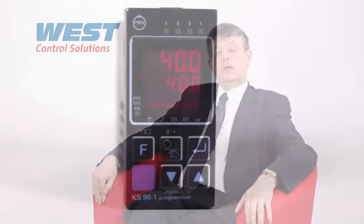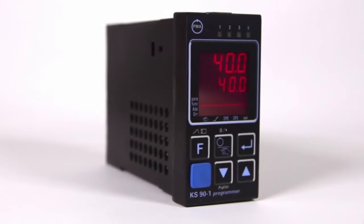An on-off controller, or signaler as they're sometimes called, will set its output so that it increases the process whenever it is below the set point. It then changes its output to decrease the process if it rises above the set point.